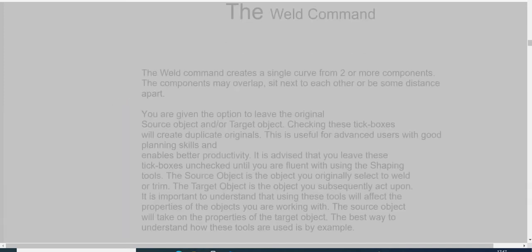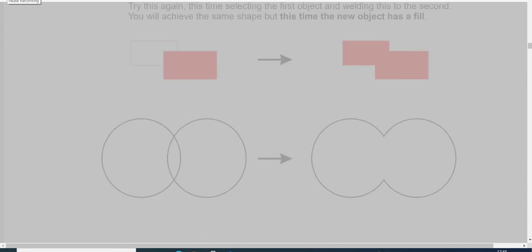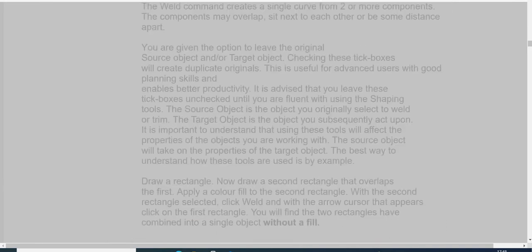The weld command. The weld command creates a single curve from two or more components. The components may overlap, sit next to each other or be some distance apart.